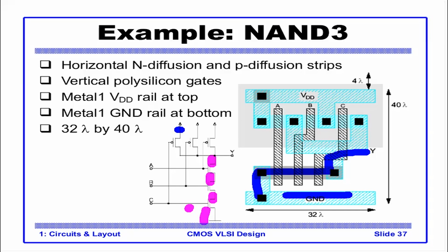We cannot see the gray part here because again this gray is same as the diffusion gray here, so it's camouflaged. VDD here is connected to diffusion by a contact. Now see here in the pull down network, we notice that the contact is needed to connect it to ground, but this region and this region here have no contact because none is needed. Right? But here in the pull up case, the VDD is connected to this contact,